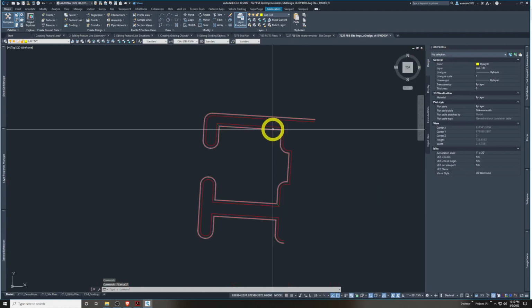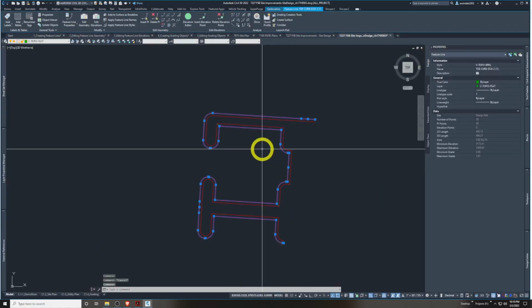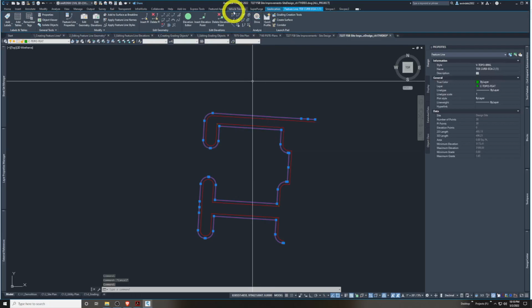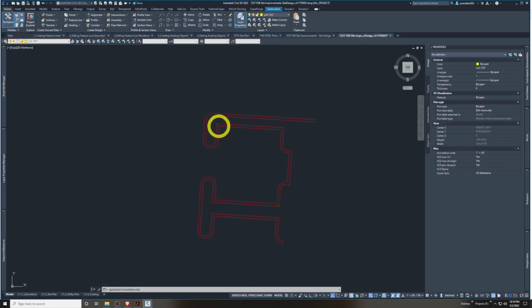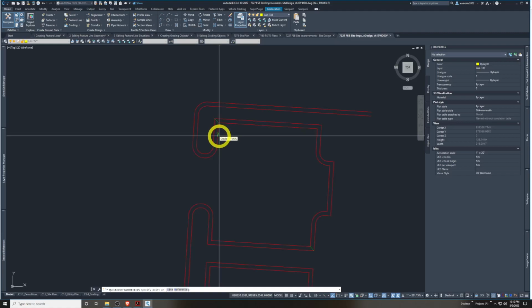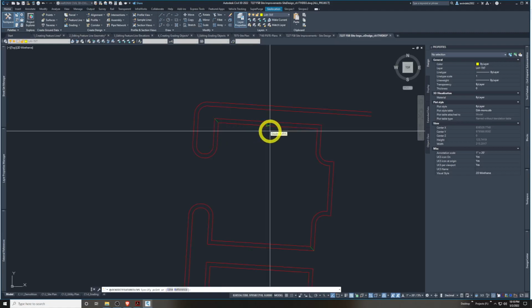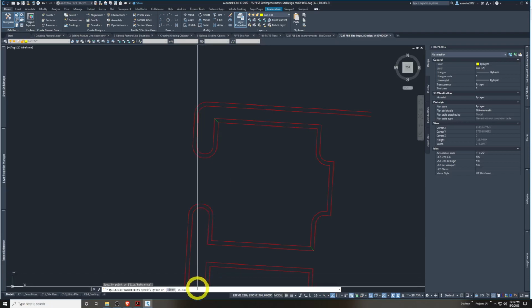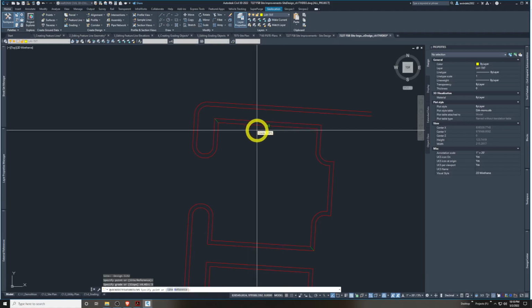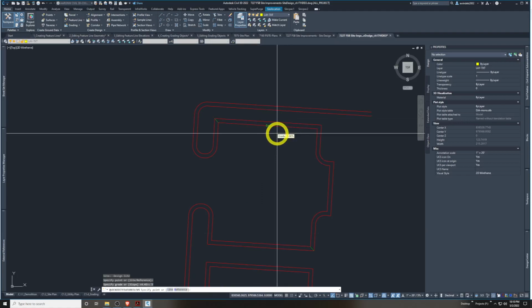We'll go back here to our feature lines of this curb I did some time ago. And this is the big heavy hitter. This one, this quick elevation edit, you can quickly edit just these single spots or the grades. I always pay attention to which direction you're going. So this one's all over the place, but if I go up in that way, I can edit this. If I pick it, I can edit that slope and uphill, say 5% instead of 4.445. There, it's changed. Or it's in this way, it's downhill.